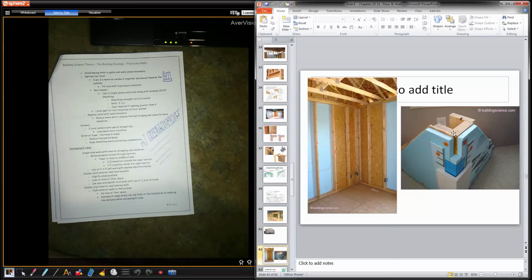And then you can see they have the corners basically created like an L, the way we kind of do it, right? I don't put that piece in place, but the reason why they put that piece in place is for this nail. This nail has something to go into. So if you're putting foam on your wall, that backing could be required. Otherwise you'd have to have a big piece of strapping, which is fine as well.